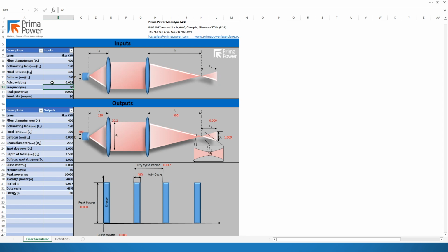If I find that the weld width is too large, I will decrease the pulse width, and if it is too small, I will increase the pulse width. This is how we would change the shape using the pulse width. Next, I will specify the pulse frequency. Again, I know from experience that a pulse rate of 75 Hz will give minimal heat input while still achieving a hermetically sealed weld at a preferred feed rate of 800 to 1200 millimeters per minute.